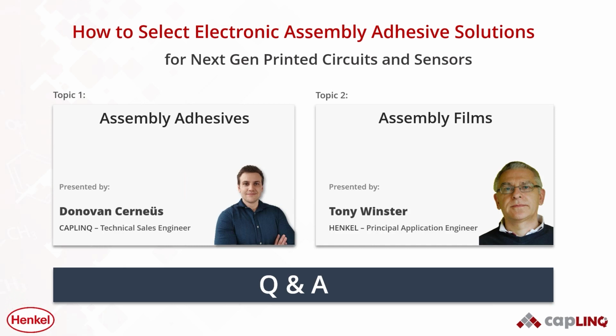For gluing down a high power electronic component and designing for reliability, how do you decide between a low CTE rigid adhesive or a higher CTE flexible adhesive? Well, I think the answer to that question is it's all application dependent. The benefit of a more rigid system is that, generally speaking, it also has a higher adhesion force, so it can more easily keep hold of the component. But the benefit of some of the, for instance, silicone materials, where you have a lot of flexibility and the ability to basically absorb stress under multiple temperature cycles, could be beneficial for certain applications. So it's really an application-dependent decision which material you would prefer over the other.